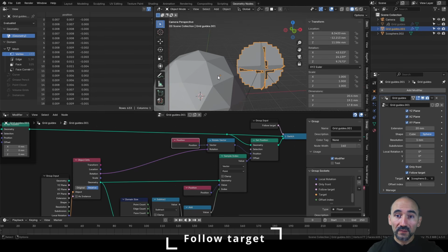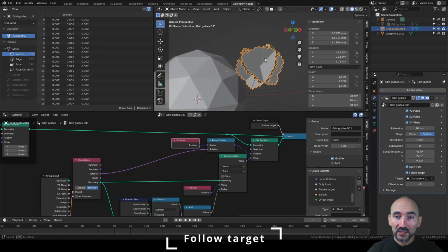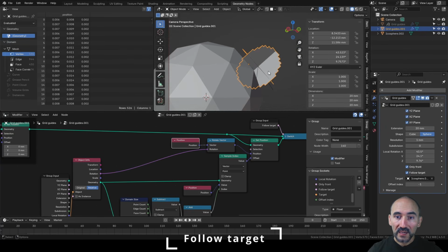But I can restore it. I can select my tool and you can see the actual rotation in the space, okay? And if I change this, nothing happens, but I can copy this information in the local rotation of the object already placed in the correct position in the space and with the relationship between its rotation and the rotation of the parent and linked target object, and I can paste these values directly in the local rotation of the object. And now you can see the correct alignment in the space parallel to the original triangle chosen for the alignment.